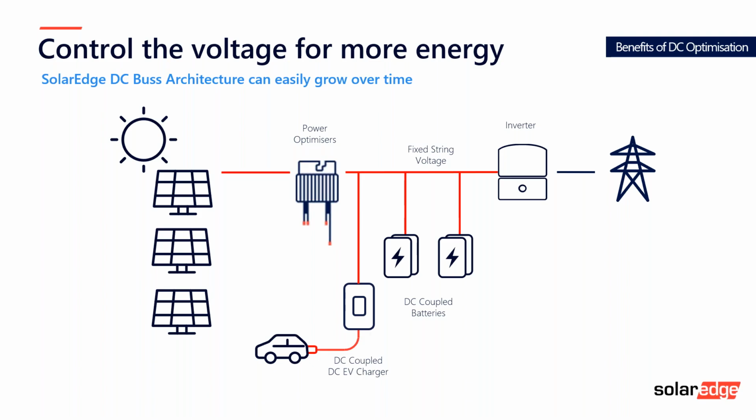And it's a significant feature that's often overlooked at the time when someone is starting out their solar journey, doesn't want a battery, looking for solar only. They discount, I guess, the features or the needs that they might need to consider when adding a battery in the future. And too often we see AC coupled systems where the batteries are permanently undercharged because there's no scope to expand that current system that's on site unless you scrap it, which is a costly activity. At least with this, we have that flexibility to expand systems easily over time.